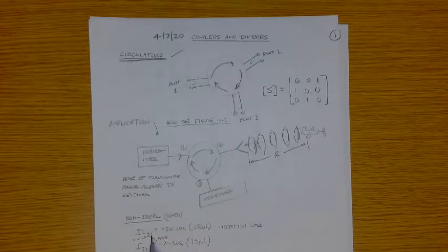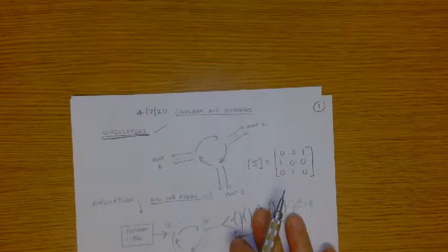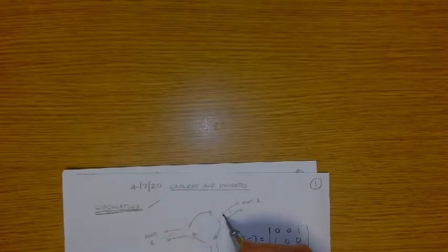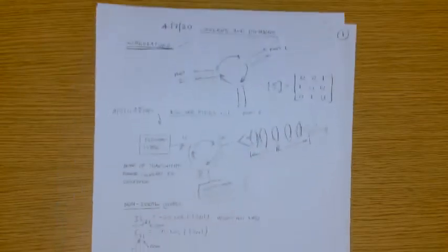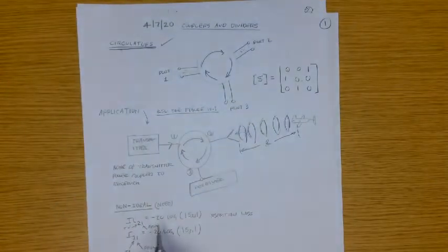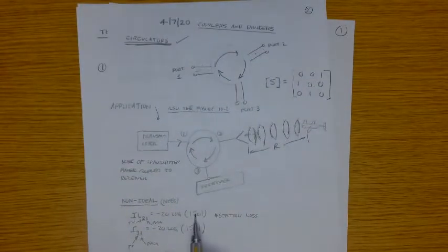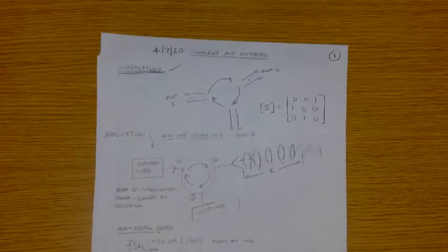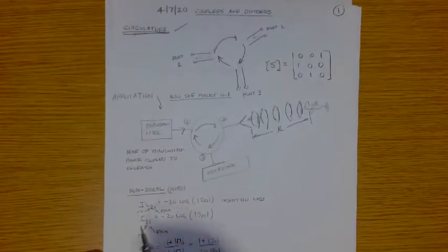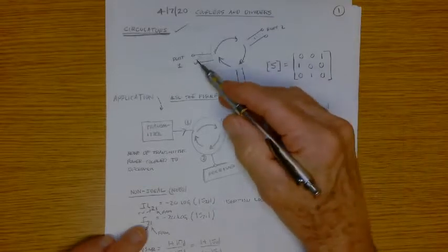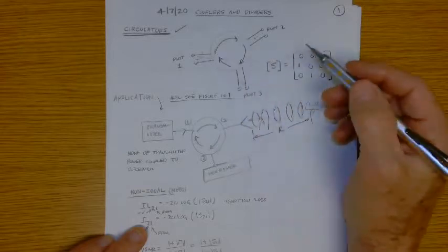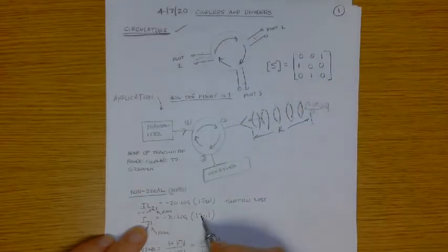So we want the insertion loss to be 0 dB, which means that in the signal propagating from port 1 to port 2, there is no loss. The device itself doesn't absorb any of that energy. Well, that's unrealistic. So the insertion loss won't be 0, but it'll be small if this thing is well designed. And then the insertion loss from port 3 to port 1: we don't want anything out of port 3 that we put into port 1, and so ideally that'll be 0.